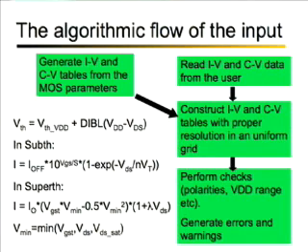Just to give you an idea of what kind of MOSFET model we are using in PETE, I have a set of current voltage equations which show the dependence of IDS, or the drain current, on the VGS and the VDS in our model. In the subthreshold region of operation, we assume an exponential relationship which is characterized by the subthreshold slope S and also the off current of the device. In the superthreshold region, we assume velocity saturation of the device, and the equation here essentially shows that we take a velocity saturated MOSFET with a lambda parameter, which gives us the early effect in this kind of MOSFET devices.